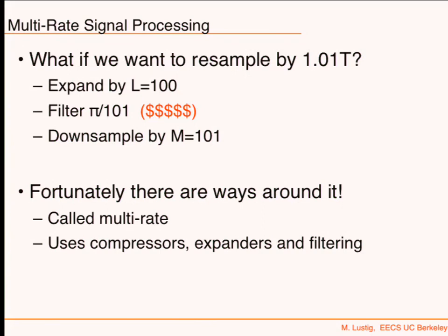And you can do that in a digital domain. So it's really, really useful to be able to do these. Also, changing rates, as you've seen, downsampling, upsampling, they're all very useful when you want to interface to hardware that can only accept that kind of rates, and so on and so forth.